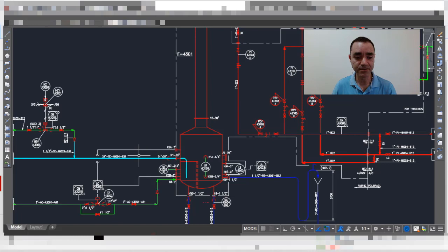So in this case, my header will release the combustion or the flammable gases through a seal of liquid, and when the mix passes through the seal of liquid, it goes to the flame tip and will be burnt, and if a flame returns, the seal of liquid will be responsible for not letting any kind of issue or accident happen in this system.